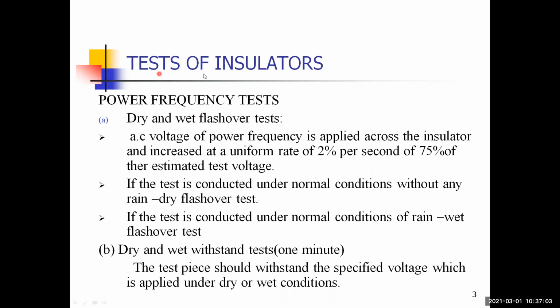Tests of insulators under the power frequency test: the dry and wet flashover test is one of the concepts. AC voltage at power frequency is applied across the insulator and increased at a uniform rate of 2% per second, up to 75% of the estimated test voltage.